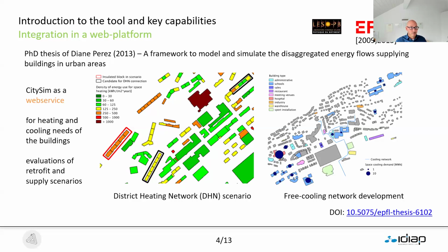So it has a front end where you can see the buildings, you can click on a building, you can see the information of the building, and you can click on a simulation button, and then you get the heating and cooling needs of all the buildings computed by CitySim. And you can, in the platform, play with different retrofit and supply scenarios. You can connect the buildings to district heating networks or to very simple boilers, and you can see the effect it has in the simulation of CitySim.